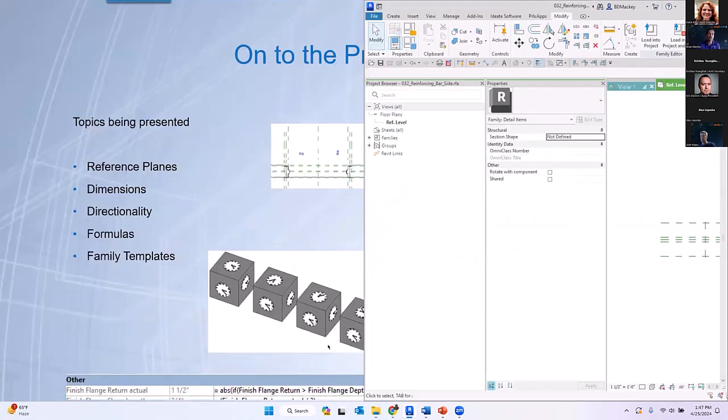I had to create 3 levels of nesting to make it happen when loaded in. One for the angle for the strut, another for the rotation. So if you want something to rotate left and right in plan, you might need to nest a family that rotates 1 degree, then load that family and nest it into another reference line that changes the rotation. So I could have a pipe that not only tips in and out, but rotates around as well.